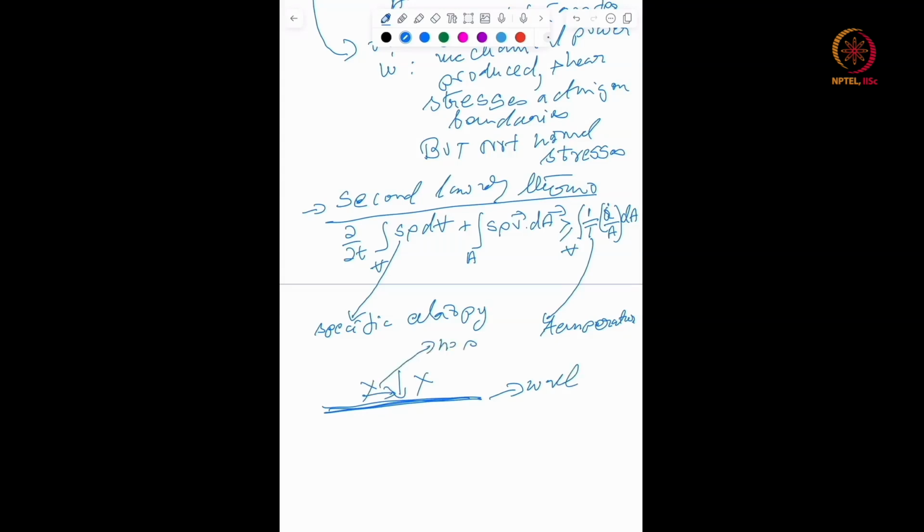These are additional conditions that you incorporate, which basically tell you that the relative velocity normal to the contact surface vanishes. And no slip says that you cannot have relative velocity tangential to the contact surface.